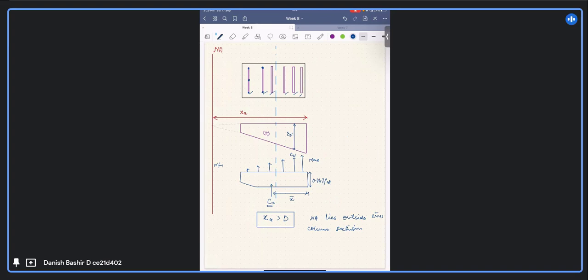ASI, for example, we are taking this as the ith line of reinforcement. The area here is denoted as ASI. For example, we have one rebar here, we have another rebar here. It has area AB, here it is area AB as well. ASI will be equal to 2AB. That is the area of the steel bars in the ith line.